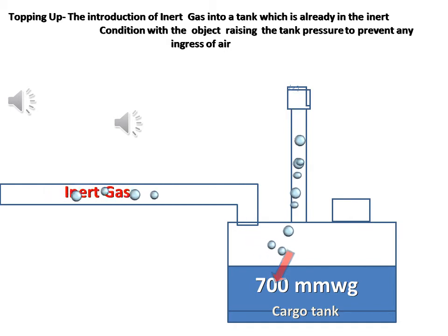Before starting discharge operations, reconfirm that all cargo tank openings are tightly closed. Cargo tank inert gas supply should be correctly set. The individual cargo tank inert gas valve key is to be kept within the control of the chief officer.